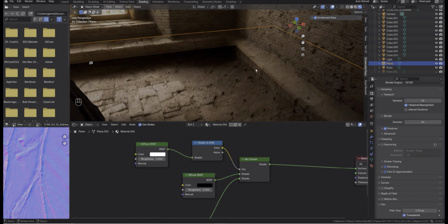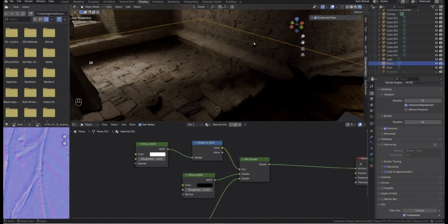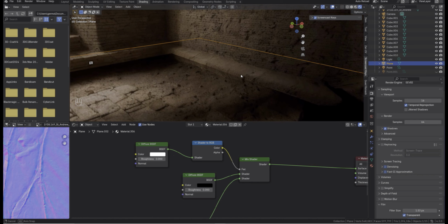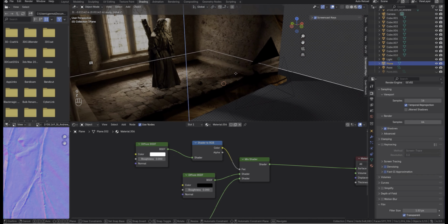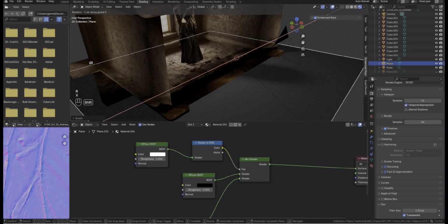We do, however, have this particular edge right there. That edge is tricky to remove because the geometry there, if I start to push this plane down, starts to hit the geometry that's down there. What I want to do is just press R and X for the X axis. I'll rotate it a little bit, pressing Shift to slightly move this. And then we get a bit of intersection there. Okay, R, X, Shift, move a little bit, and I guess we're getting less of it. I can also type in the values, but I want to eyeball it.